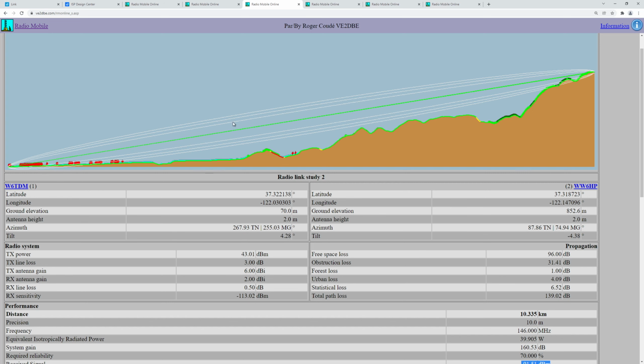In this image as well, you can see the Fresnel zone. They have the Fresnel zone in here for the spreading between the transmitter and receiver, and this just gives a nice visual representation. You can also see different ridges, so if you selected a site that was not line of sight, or you had these hills a little bit higher and they intruded into the Fresnel zone, you could see how that impacted the actual performance of the system, so the reference attenuation would change in that case.